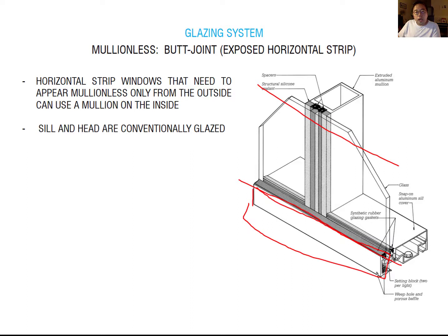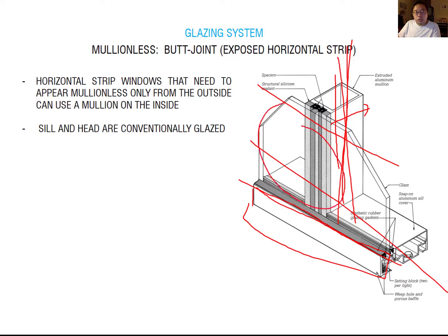from the outside. However, inside they're using this vertical mullion. So when you see from the inside, you can still see these vertical pieces and this horizontal mullion together. But when you're making a high-rise building, sometimes the butt joint doesn't work because it's too weak. So that's why you have to provide this vertical mullion, but you don't want to make out this vertical joint from the outside. This region is a little bit set back from the finished level, and then it has some glazing system over this vertical frame.